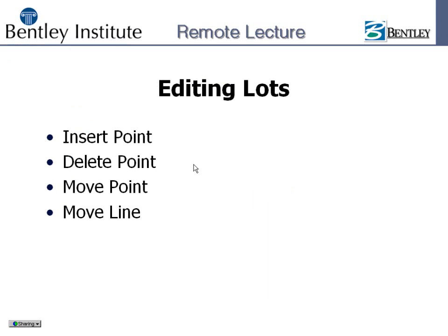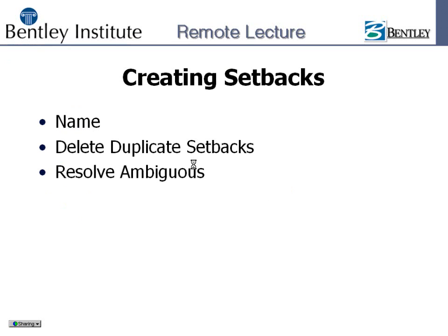Now I'm going to show you the creating of the setbacks. Pretty neat little feature. Not sure you'd really want to have horizontal alignments for setback, but what this is going to do is, because a lot of times you're going to offset the lines and have them in there, and then just plot them out. You really don't care to have them have horizontal alignments with this, but I don't know any other way in MicroStation to offset an element with multiple offsets on the sides. So this is a pretty slick little tool, okay? And then you also have the added features of reporting and doing offset points and things like that.